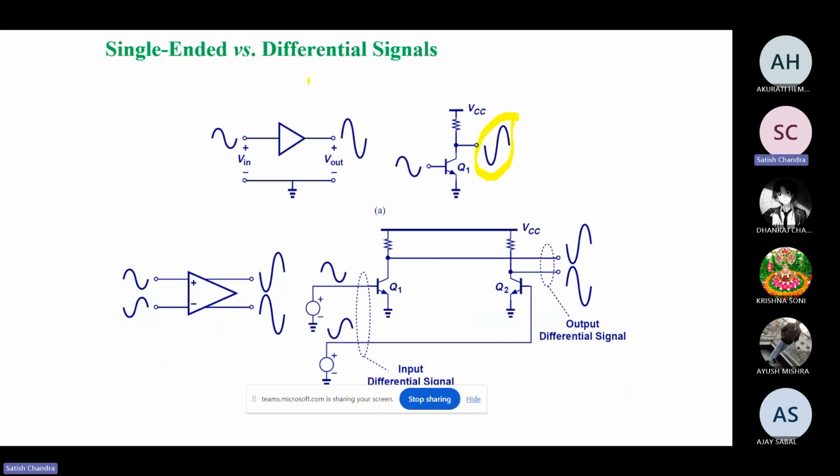And what about the differential signal? As we talked about in the last slide, we can generate it by a transformer, and also by a double-input op-amp. Later on we are going to study this part also, but up to that we are going to see this. If we utilize the signals 180 out of phase, that is going to give an amplified version of this one. And if I subtract the signals from each other, it is going to give double of that. That is the basic thing.